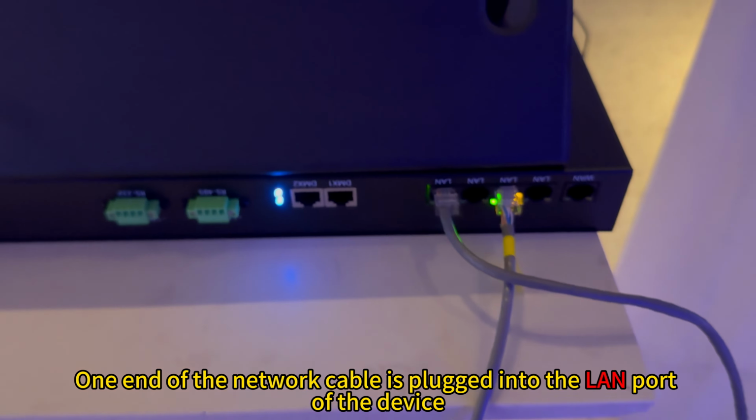Double-click to open the browser on the laptop. Enter the device's IP address here, 192.168.46.19. Then followed by a colon, 1880/UI. This URL is designed to facilitate our calculation of the on-site offset. The part after the colon is fixed, and the front part here corresponds to the IP address of the device.